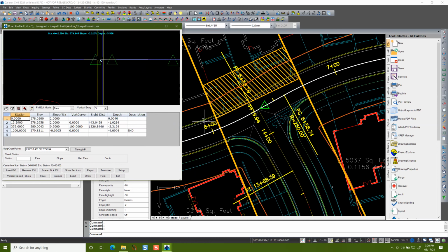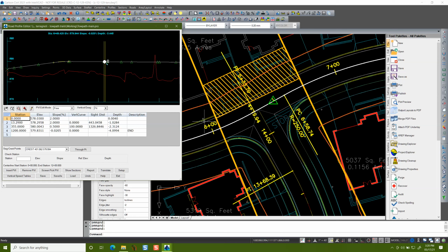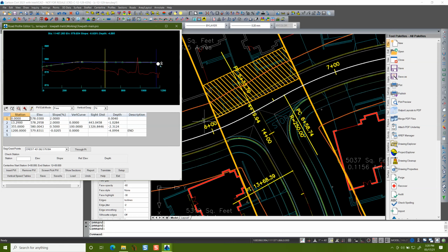When we saw the other road, you saw how high it was over the existing ground, and it was consistently almost flat out there. That's because where this one ends right here is where the other one starts, and it has to go throughout its length and tie back in right where this one is. So that has to be the same slope, and it continues.